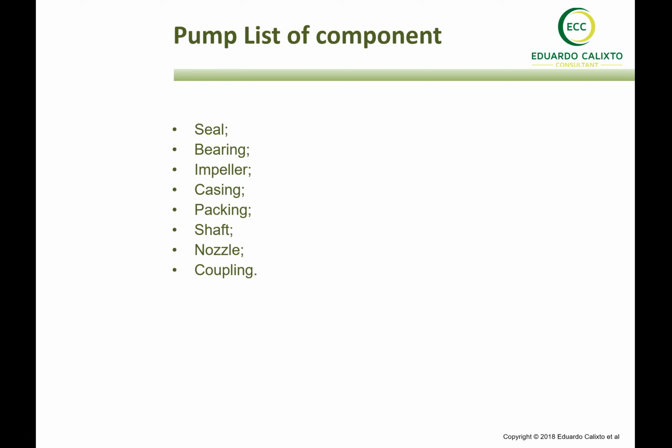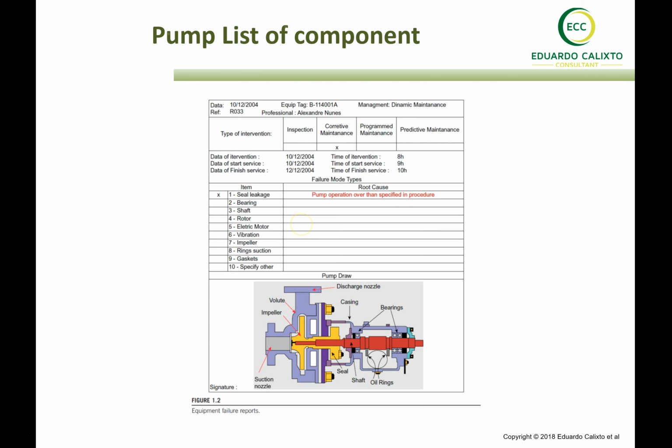And the RCM is very important to do at component level, and also consider the failure modes, because we will be very clear on the specific maintenance tasks that need to be carried out in order to detect the equipment damage and deterioration and avoid such failures happening.